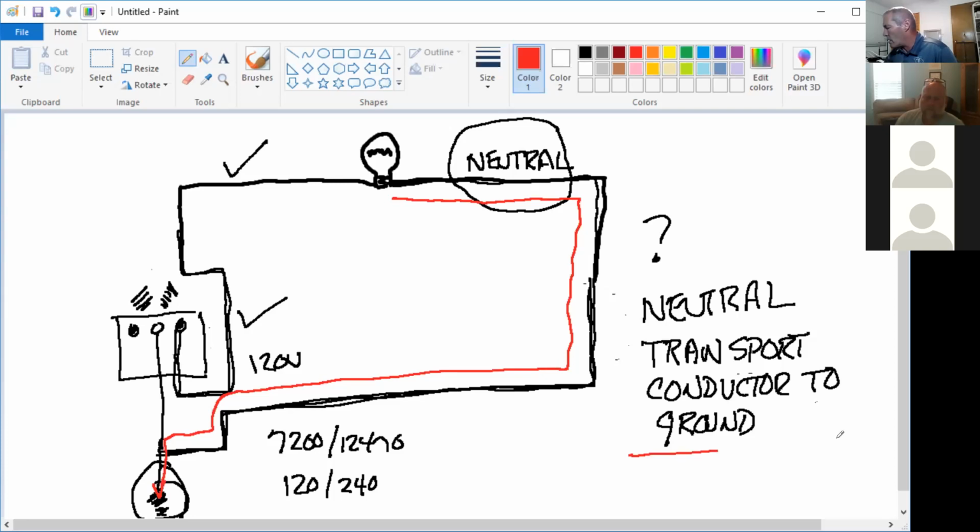Any questions there? I've got to have a complete path. Getting my voltage out on an energized wire, that's fairly simple. Do remember, I've also got to get it back to ground somehow. That's why we use a neutral conductor to make a conductive connection or a wired connection back to ground down here at the bottom.